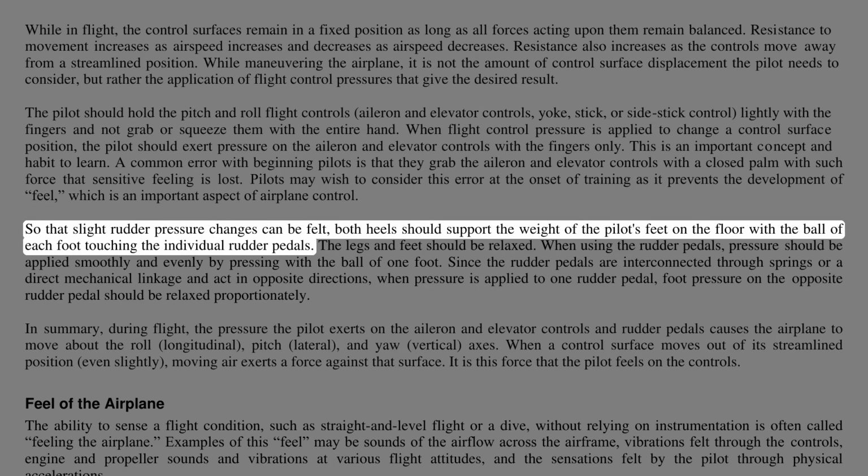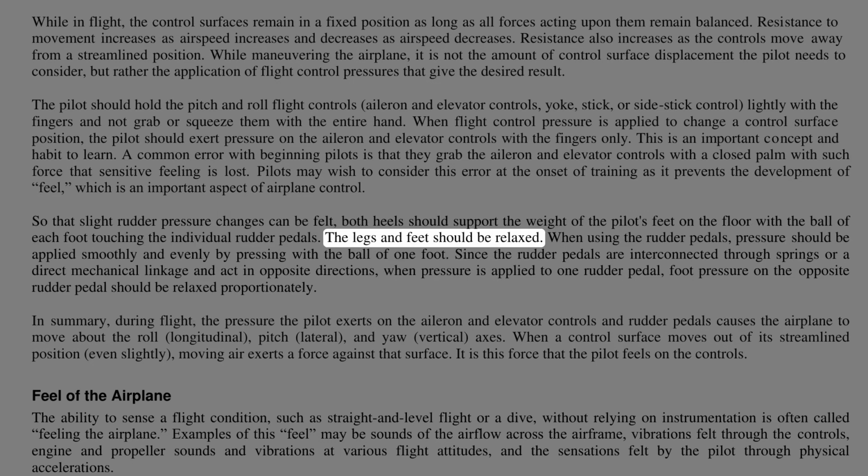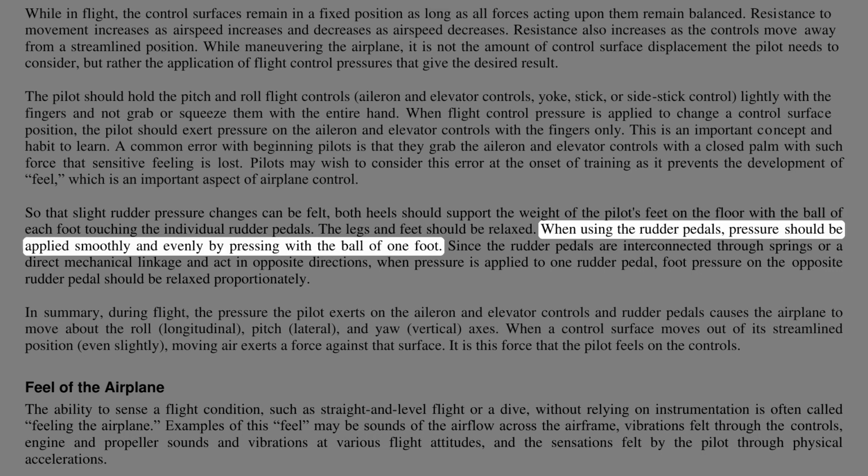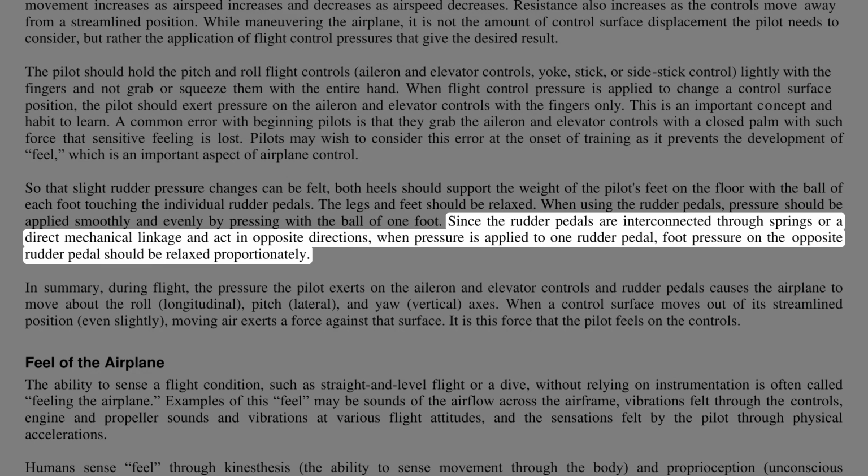Both heels should support the weight of the pilot's feet on the floor, with the ball of each foot touching the individual rudder pedals. The legs and feet should be relaxed. When using the rudder pedals, pressure should be applied smoothly and evenly by pressing with the ball of one foot. Since the rudder pedals are interconnected through springs or a direct mechanical linkage and act in opposite directions, when pressure is applied to one rudder pedal, foot pressure on the opposite rudder pedal should be relaxed proportionately.